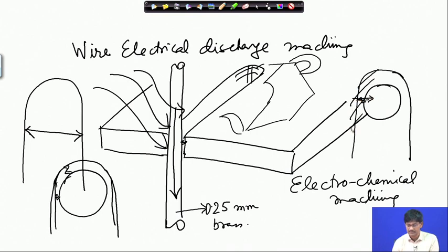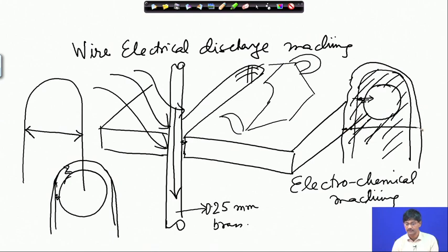So, if this place is filled up with fluid, you really do not have a choice, and there might be totally uncontrolled cuts, and you might end up with large overcuts. Therefore it is not very well controlled, and that is why wire electrical discharge machining has been widely accepted while this has not.